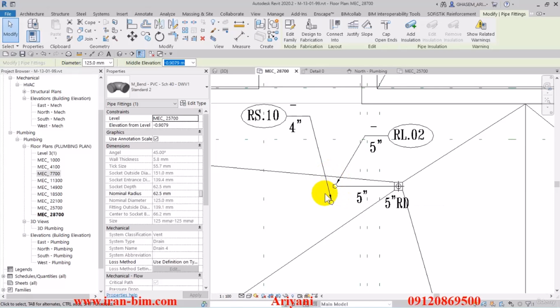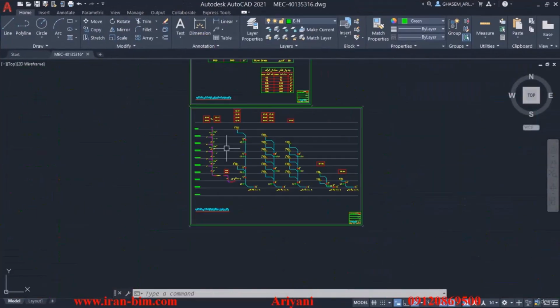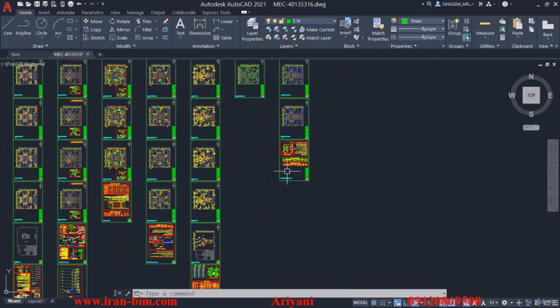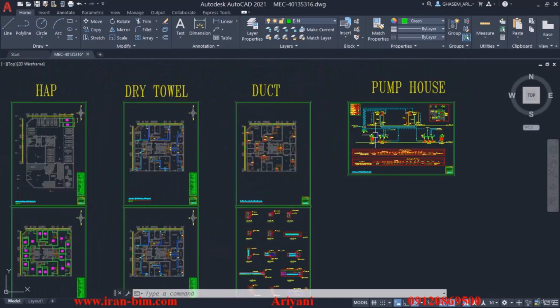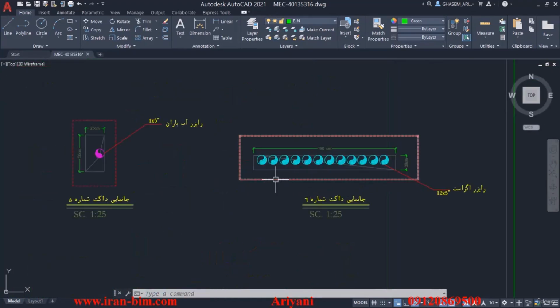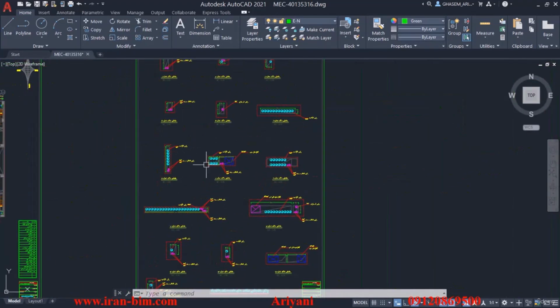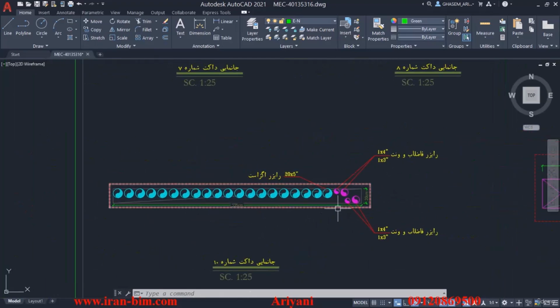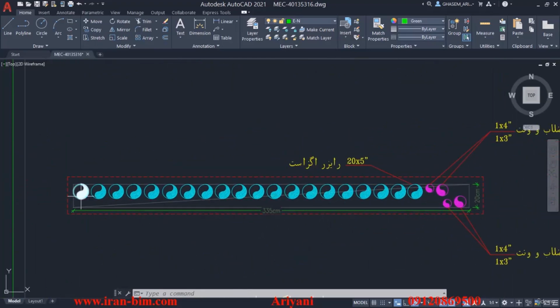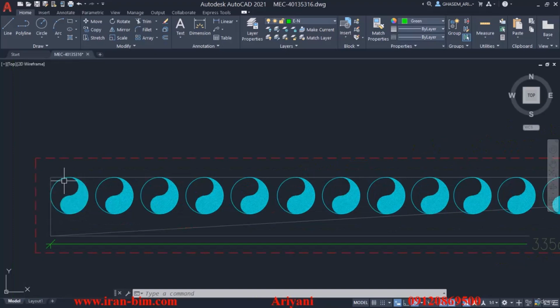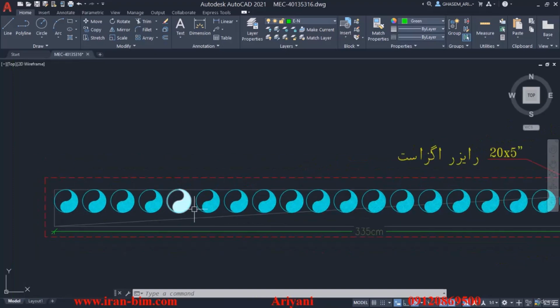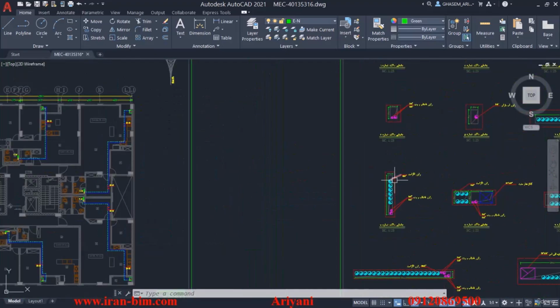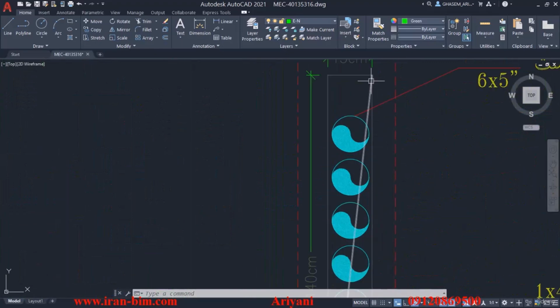And where you're drawing the plan, you need to make sure, is this area enough for about 10 of these supports or not? Because in a lot of the cases in the AutoCAD file, we can go over here to see your example right here. So this is not actually possible or logical. They fitted the pipes cleanly in them like this, and it's because they just calculated the diameter of the pipes and then drawn. They haven't actually paid any attention to the area that the support needs.